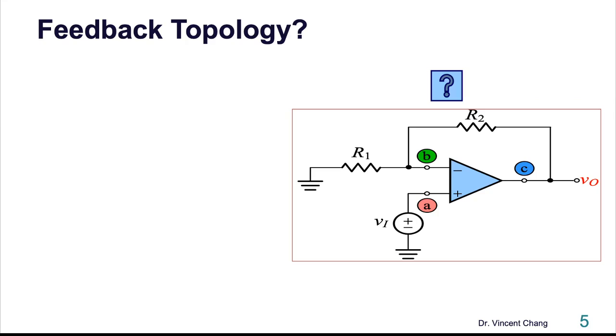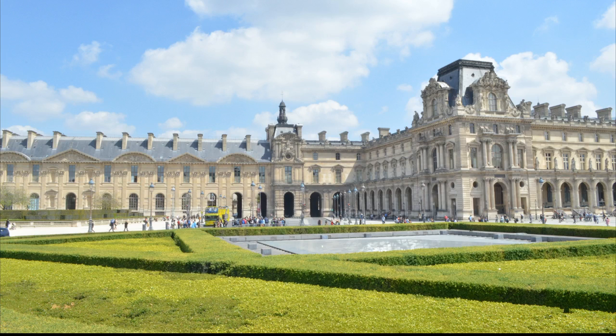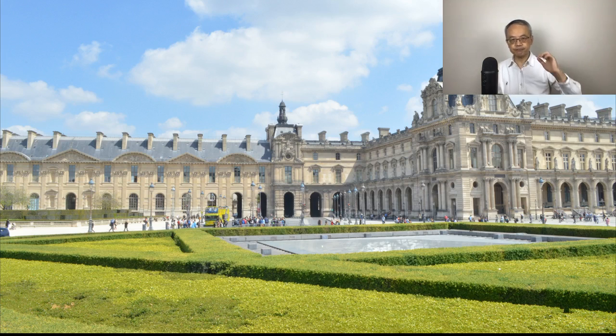What kinds of mixing at the input side and what kinds of sampling on the output side? Make sure you can identify the circuit I just mentioned, a non-inverting amplifier. I want you to associate the circuit with the feedback topology. Just redraw the circuit in your notes and think about this for a few minutes.